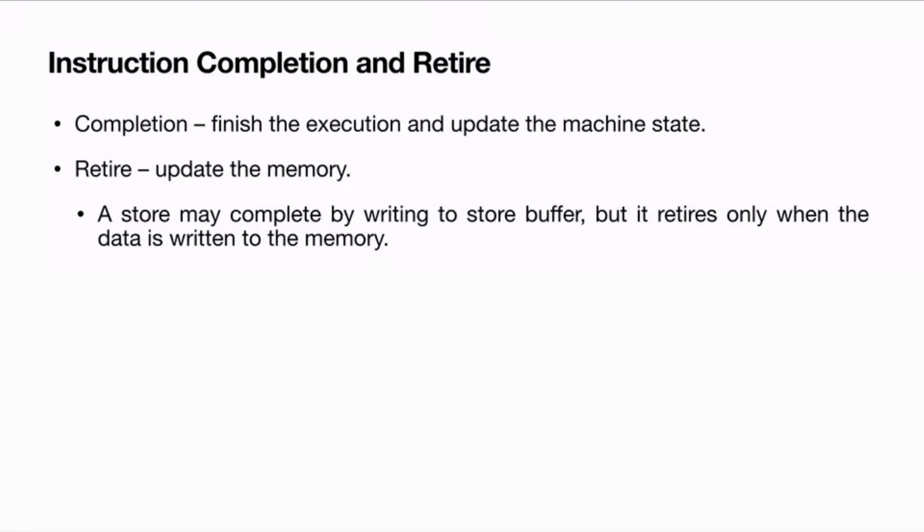Of course, a buffer access takes less latency compared to the cache or the memory access. Because of that, we'll be writing the stores into a store buffer in the completion stage. But from this store buffer, we'll be writing to the memory or the cache when the cache or memory is available. So that can be done at a later point in time. Otherwise, if the store buffer is full, then we have no other option. We have to write it. Till that time, we can keep accumulating the stores into the store buffer.